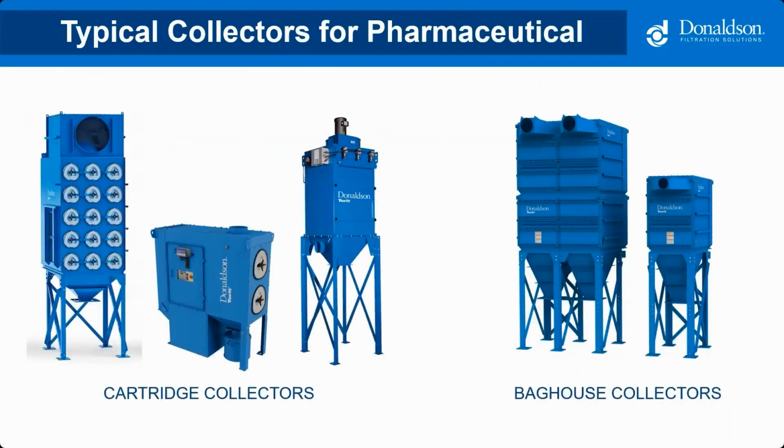When we look at pharmaceutical applications, most of the time you're going to be dealing with cartridge collectors. If you're dealing with a particularly sticky or moist dust, that's where you may want to bring in a specific type of baghouse that uses wider envelope shaped filters. That's the best option for that sticky, hard to clean dust.